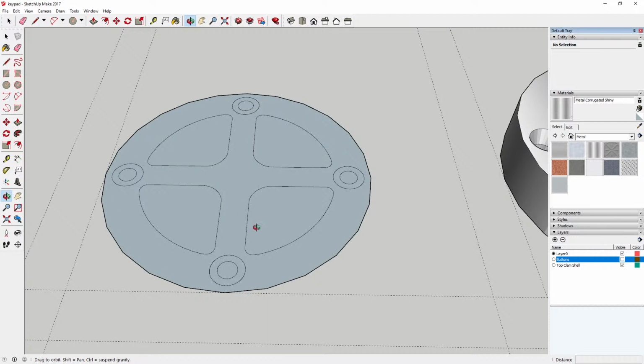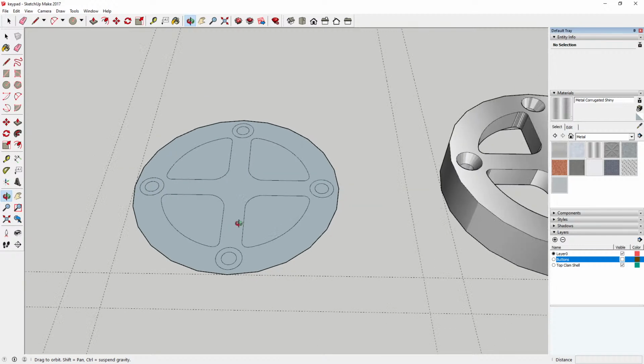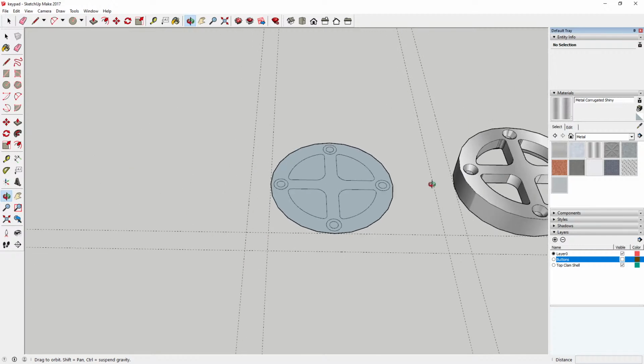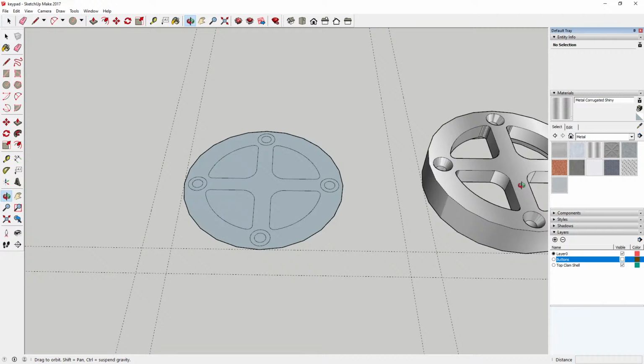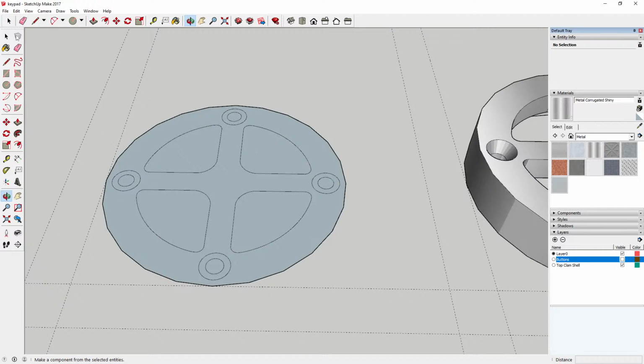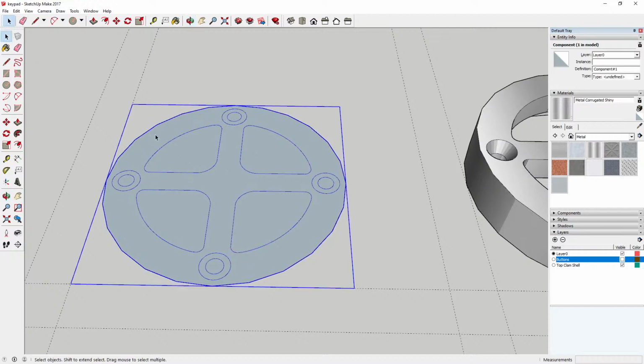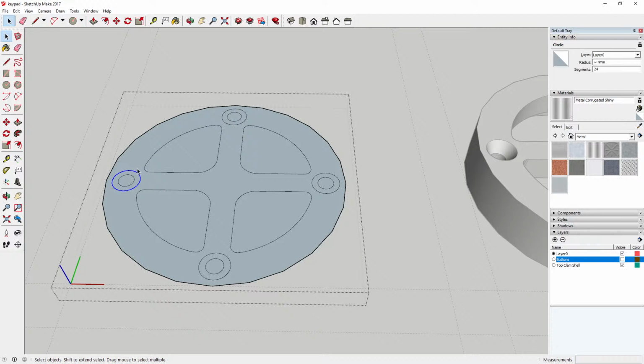So we've got our back plate. Needs to be milled, the opposite of this really. So let's say we know it was going to be 12mm. These don't need the countersunks, so let's go into this. So I don't need the countersunk on the bottom.